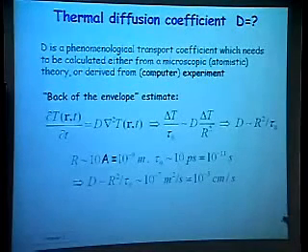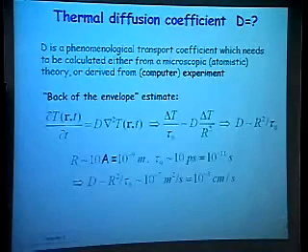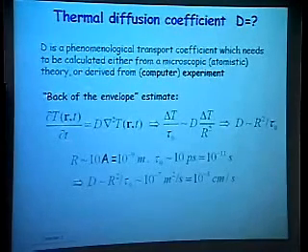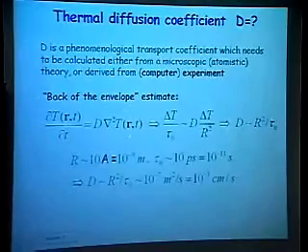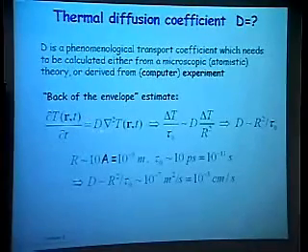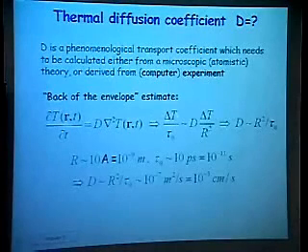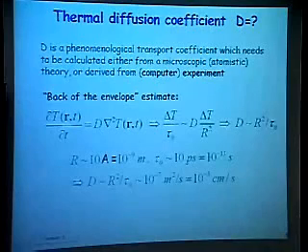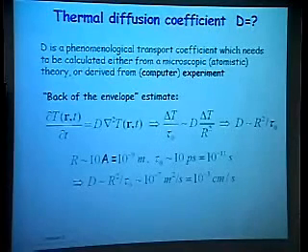So if you want more precise answers and get the right prefactors and everything, of course, you will have to solve the equation. So let's start from the heat transfer equation and write it down in terms of finite differences. Here we have the rate of change of a temperature, which is delta T over tau 0. Who is delta T? Delta T is just the temperature difference between the initial temperature of a protein and the temperature of a bath.